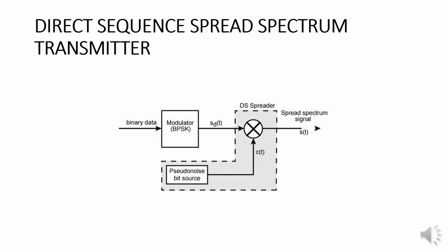Here the transmitter may modulate the baseband signal m(t) with binary phase shift keying. The modulated signal x(t) has a wider spectrum than the binary phase shift keying of b(t), but still x(t) has either 0 or pi phase.